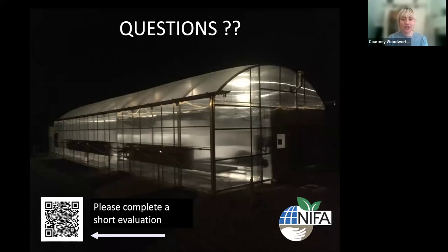And then the last question, is there a better color to use with the twin wall: white, clear, or bronze? Ah, that's a great question. So yes, I'm very glad that question got brought up. There are greenhouse companies that sell bronze and opaque twin wall polycarb. The reason they're doing that is because people are using it as a head house in their greenhouse, or they'll put it over a storage area, or maybe where your aquaponics section of the greenhouse is going to be. Those products are not made for growing plants underneath them.